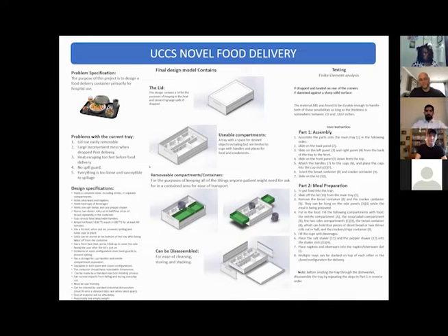After doing the hand calculations, we got that it should be between 0.02 and 0.1837 inches thick. Somewhere between there will be fine to fall. So in the end, after 3D modeling it and getting the numbers a little more condensed in SolidWorks, we ended up picking that most of the things would be 1/8 or 3/16 of an inch.